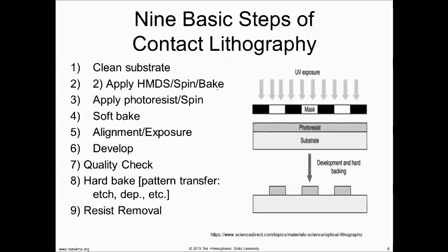My photoresist is an organic polymer, so it's a photoactive paint. But with my wafer, you might not think this, there's always humidity in the air. My wafer has dangling bonds, so water vapor actually sticks to my wafer. This is similar to taking a hot shower in a bathroom: your mirror is cold and you see it all foggy, because the water vapor sticks to it. In that case, if we spray painted over top of my mirror, the spray paint wouldn't stick. You wouldn't think of that, but on the atomic level, this is my analogy, my wafer is wet from the humidity.